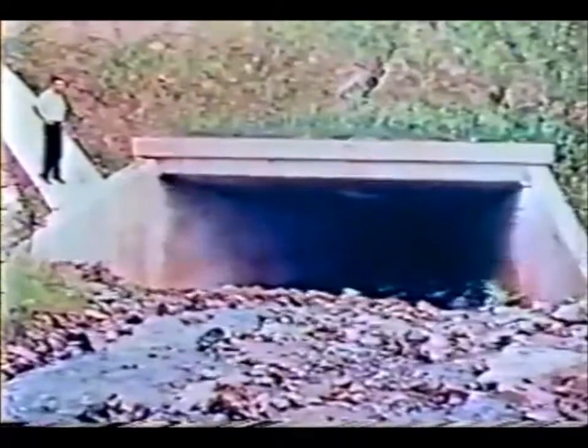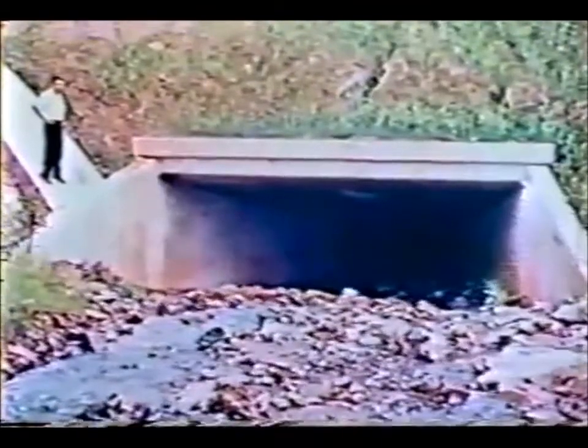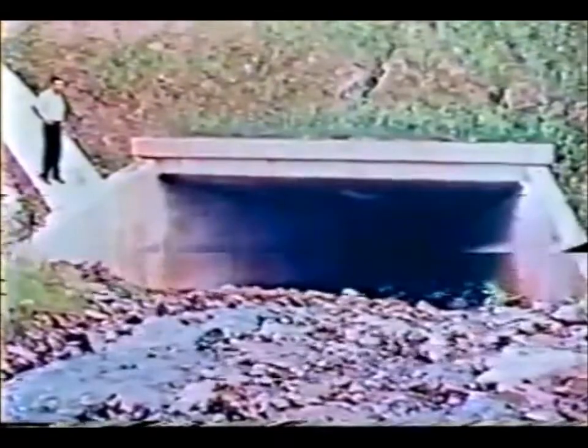For example, in North Carolina, a box culvert was reduced from an 8x5 to a 5x4 by adding a slope-tapered inlet. Near Bryson City, North Carolina, a savings of 54% was made on the construction cost of one culvert.